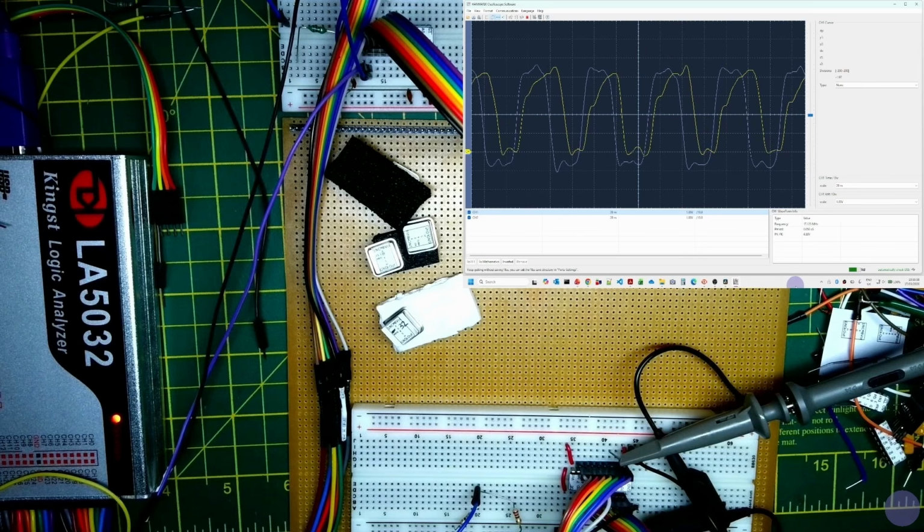Welcome to Breadboarding. In the previous video we tested out some buffers and latches, and we also tested out our bus rails here, which is the stripboard bus rails with our various rainbow DuPont connectors. And we were able to run this using a variety of different crystal frequencies, and the highest frequency we managed to get working was a 66 megahertz one, and this meant that our A0 sort of simulated address line was a signal of about 16 megahertz.